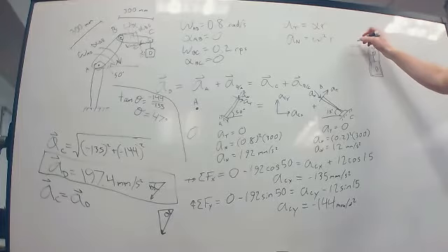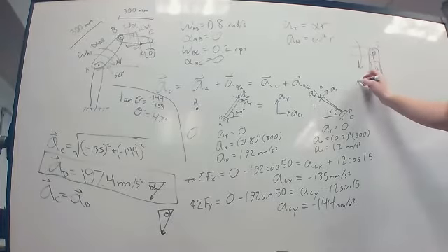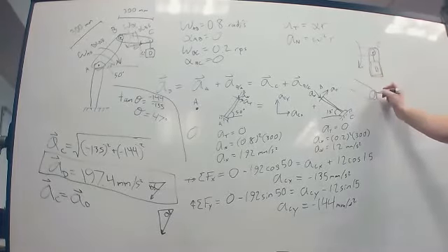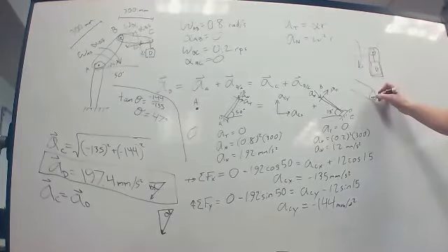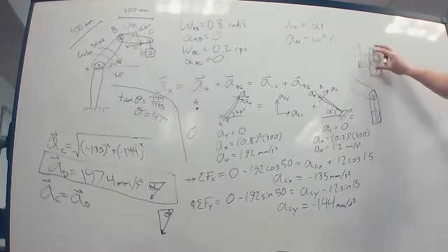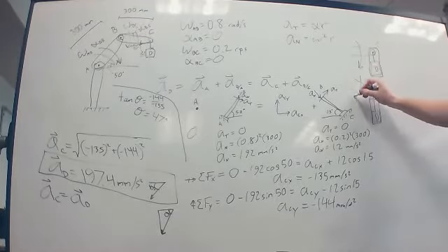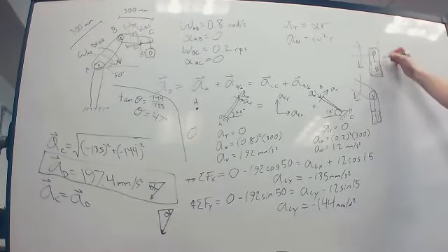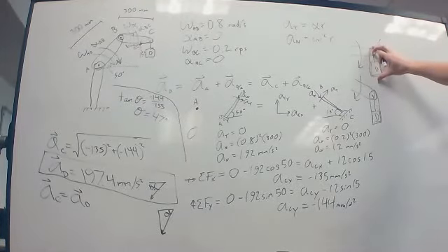What that means is that this whole piece right here moves as one stationary thing. So as C turns this way, and C is now lower, CD still looks like this. And so this whole object here has the same acceleration. The acceleration at C is the same as D because this is like a rigid piece that doesn't turn. It remains vertical.